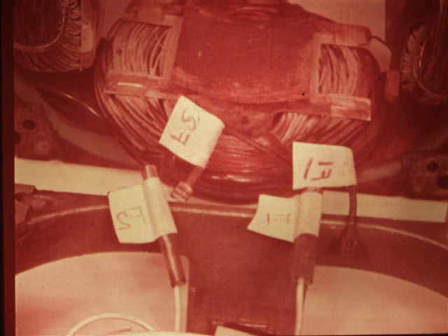Now, disconnect the field leads from the rectifier in the housing. Be sure to mark the leads and terminals for identification. If they're crossed at assembly, the generator won't work. Test the field for grounded or open windings. Use the same ohmmeter or powered test light.